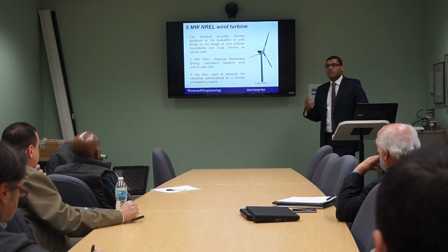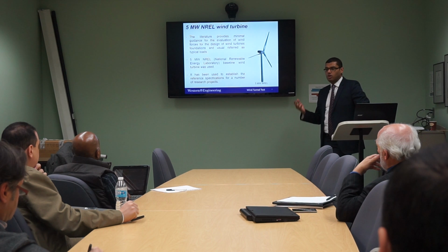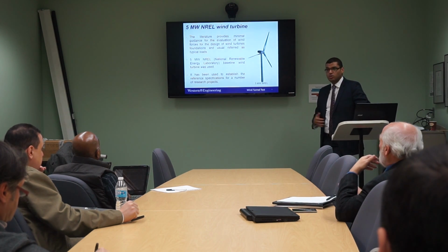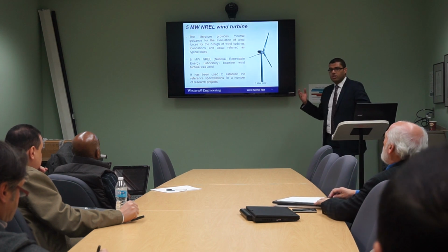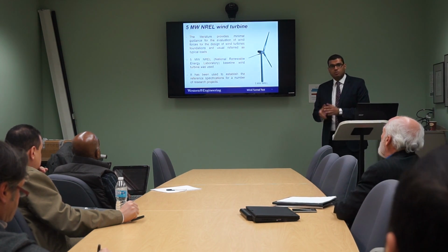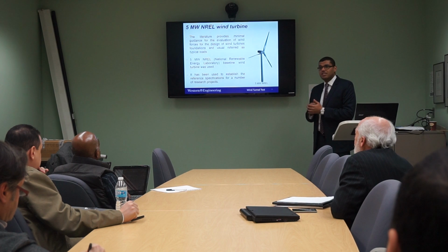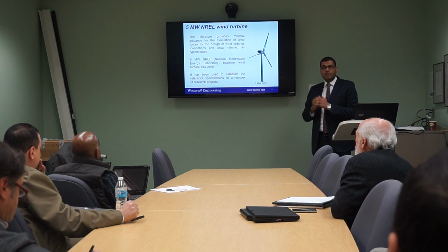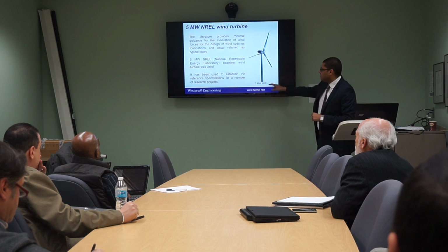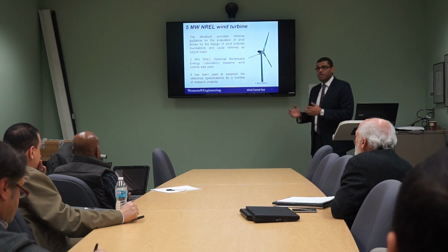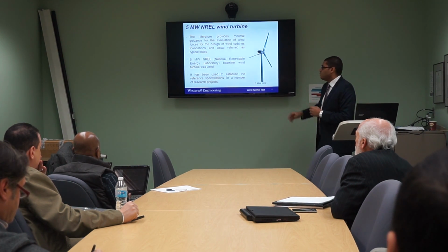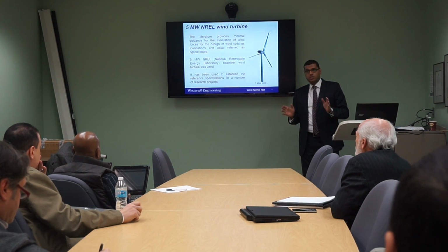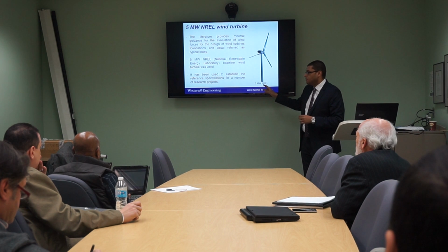Unfortunately, there is minimal information about the actual loads at the foundation coming from the wind turbine, and they usually use typical loads. So that's why we are making the wind tunnel test, to be able to get accurate load at the base of the wind turbine to apply in our finite element analysis. We adopted the 5 megawatt NREL wind turbine as our reference wind turbine to calculate the loads here. This is not an actual wind turbine, but a wind turbine for research purposes represented by NREL.